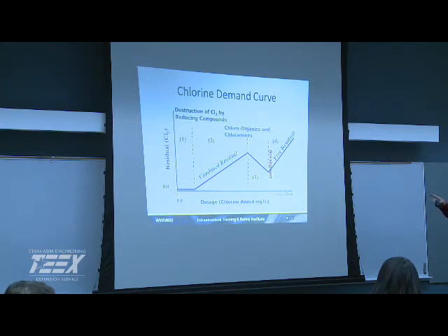Because most people, when they start getting calls, hey, it tastes really bad, tastes like swimming pool, they're like, well, we need to back off, we're feeding too much. No, you got to feed more. Because once you hit break point, now you're not going to have those taste and odor issues unless you're really, really high. So once you hit break point, now as you increase your feed rate,